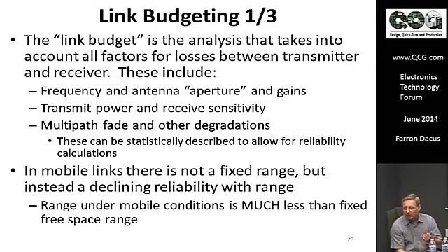That includes the transmit power, the antenna patterns, the frequency you're at, and to some degree the modulation mode and the bit error rate. I'd call the power and the frequency the first order factors, and everything else kind of second order, though second order does add up.